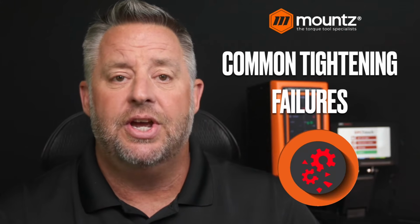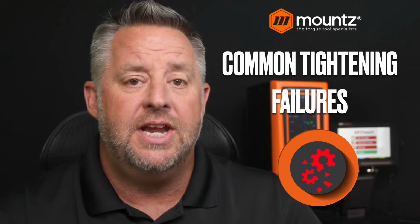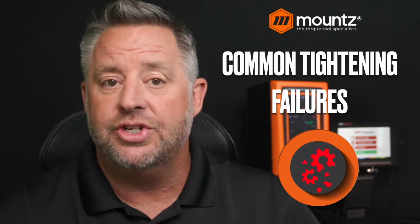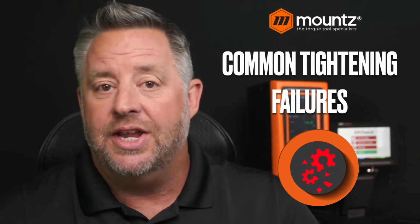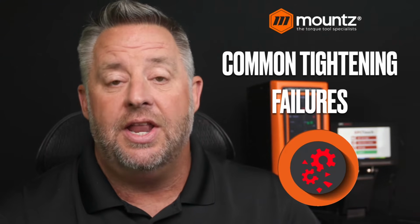All of these types of things can lead to failures, especially if we have an under torque situation. Any type of vibration is going to cause that fastener to possibly back out and then fail.